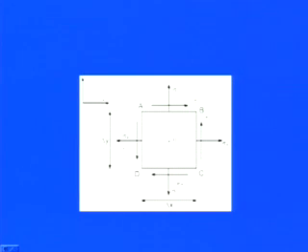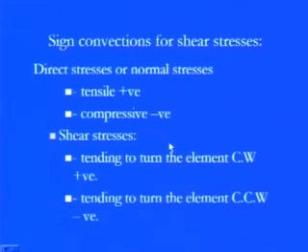And now you see, if we are saying that it is maintained in equilibrium, that is only possible if whatever the forces are around this structure, and whatever the moments are about this pivoting point O, are 0. So now you see, as we discussed, first of all, the sign conventions are there for the shear stresses, because for the normal stress component, we already discussed the sign convention.